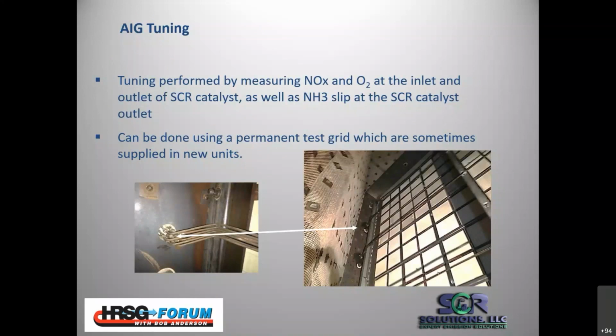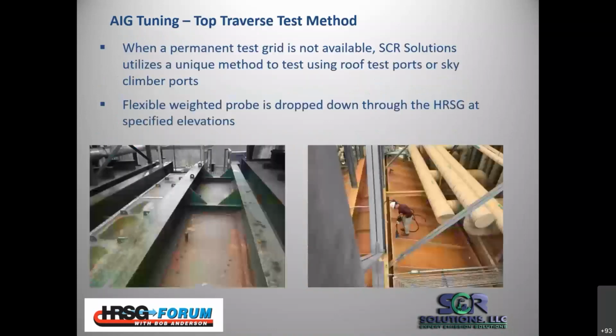They're 1/4 to 1/2 inch diameter stainless steel tubes arranged on the back side of the catalyst, at various points, elevations and depths. You bring in a trailer, draw samples, and get a somewhat real-time look at the distribution.